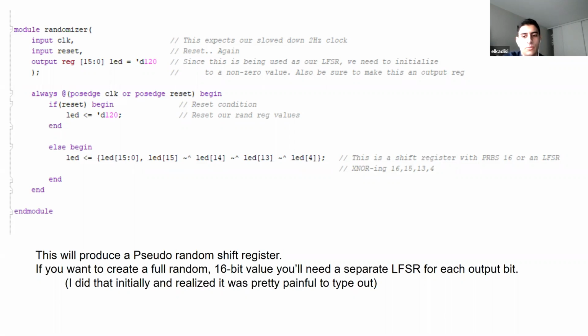Maybe you've noticed in some docs that you can put a number before the apostrophe, like 10-bit 120. You don't actually have to do that. It's kind of like the asterisk. It's a shortcut that you can use to avoid having to remember how many bits the register is all the time. Vivado is usually smart enough to realize that you mean the whole register size if you do it that way.